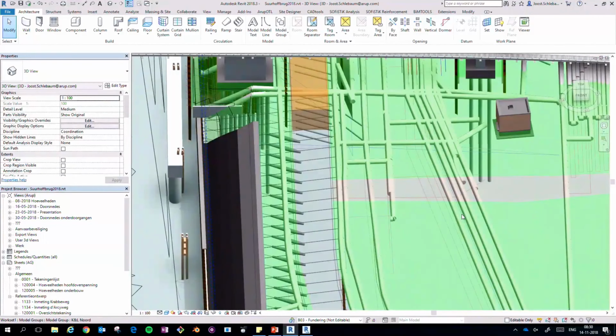And using this workflow, we could quickly shift, move the alignment, move the supports, update the bridge. We did not have to remodel one single object of the bridge. We only had to rerun the scripts after the alignment was updated and the whole bridge would update.